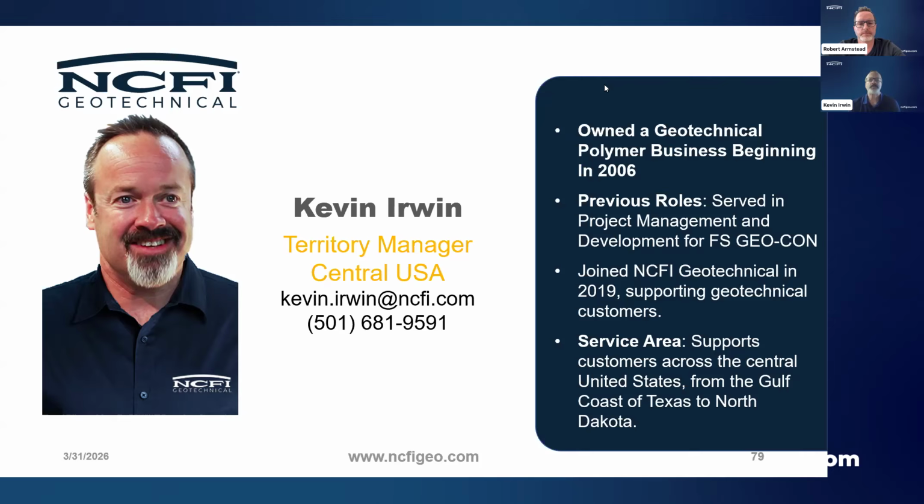Not sure. I'm trying to think of what would be milky water. It may be. So if that happened one time, it could be maybe you were a little off ratio. If you're off ratio when you inject the foam into the water, it's not going to be as hydrophobic. Some systems are not as hydrophobic as others. So depending on what system you're using, it could be that maybe that leading edge was not as hydrophobic as the rest of it, and maybe it strung out a little bit.